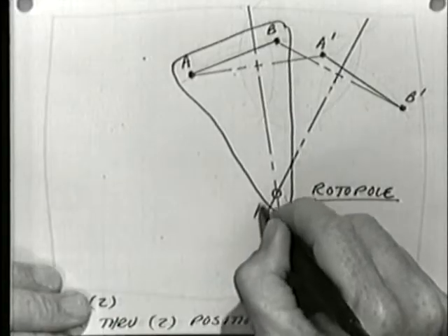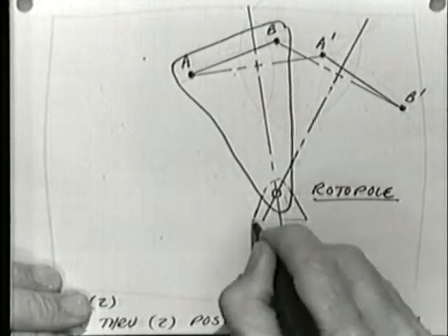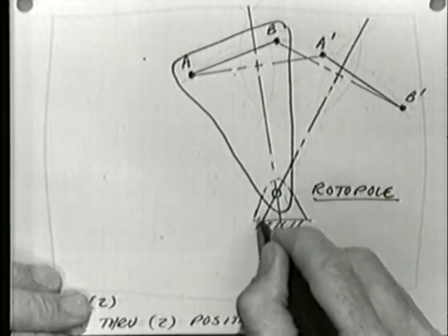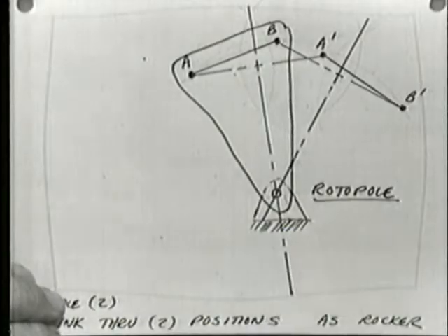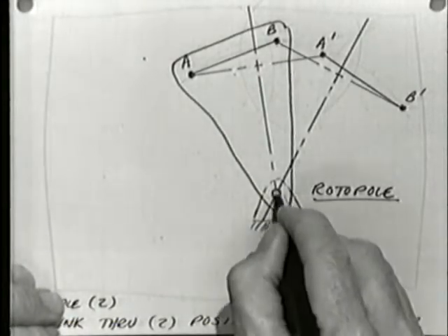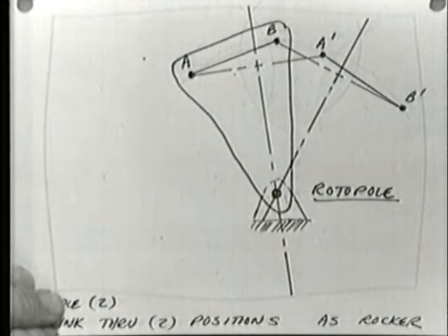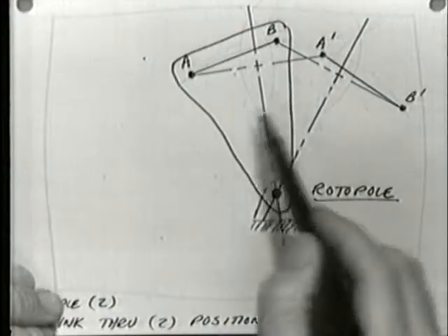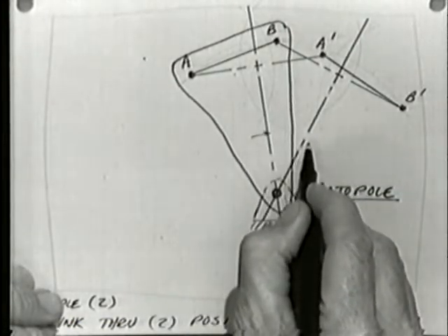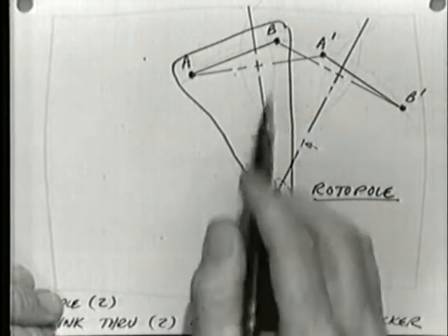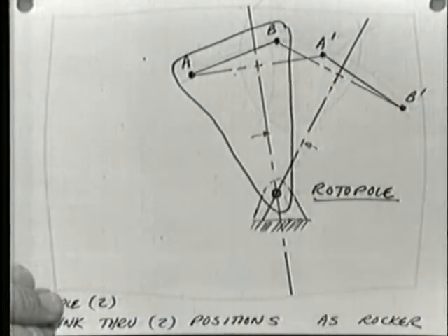I'm going to add some meat to it such that it comes down and picks up this pivot, which I will now attach to the frame, which I hope is in the right place. If it's not, I'll have to solve the problem a little differently, but let's assume that I have some machine frame available down there to attach to. So I'll drill the hole, put the pin in, and what I've so far created is a single link which will, when rotated through a particular angle, this being the particular angle right here, move the line AB into the position A prime, B prime.